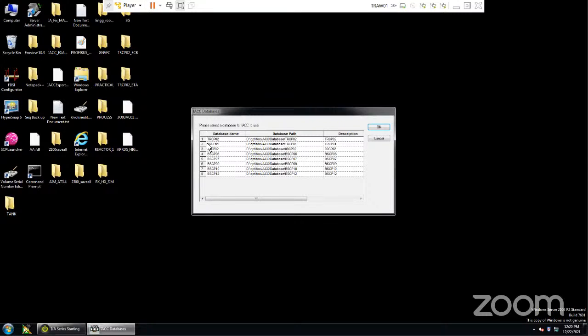So here, whenever I want to develop some logic, if you can see, it is asking me for which processor I want to develop this logic. My PC is already configured for one particular DCS architecture where we have these CPs, the control processors. If you remember, previously we discussed the control processor, inside which we ultimately keep the programs or function blocks. So let's develop some logic for the TRCP2. This is just a CP name I have defined, and I'll say okay.